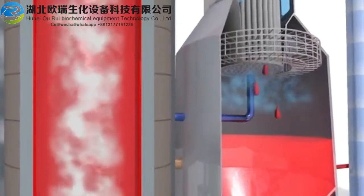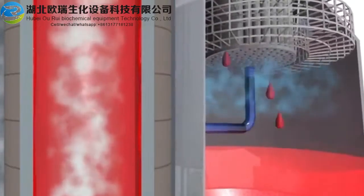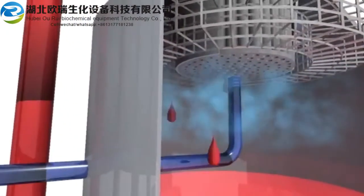For the brine that reaches the sump as liquid, it recombines with the brine already in the sump, as well as new feed brine coming into the sump from the deaerator. That mixed volume will then recirculate back to the top of the tube and shell.